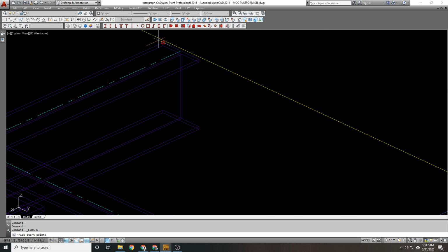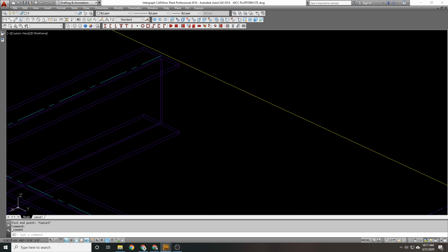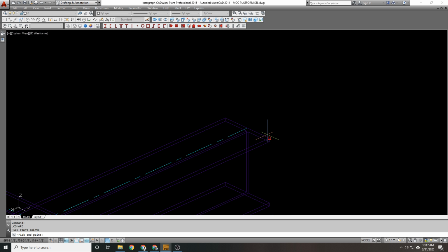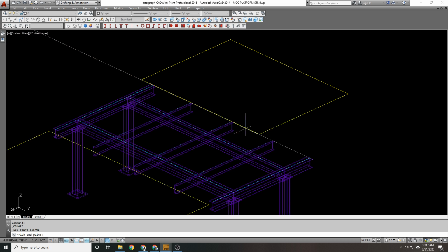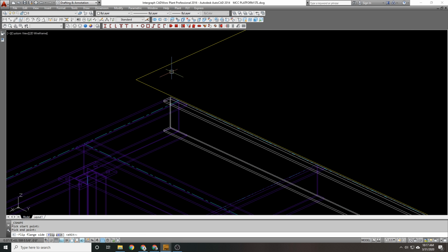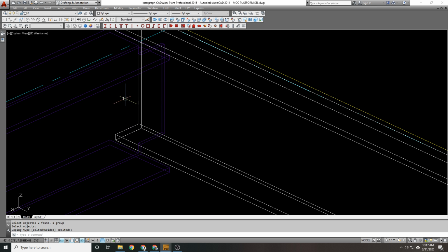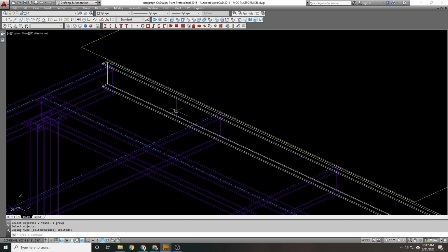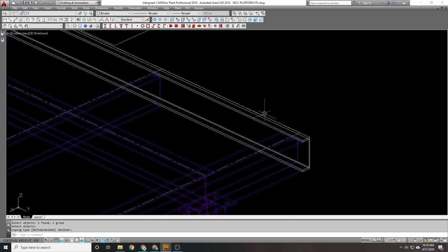So I'm going to pick a point from, again, the channel has to attach, let's see, not here, but this way. The channel has to be, oops, I forgot my rotation was still on. Here to here. And we're correct. This has to be coped into here so that we can put a shear tab here and they can access the bolts on the sides. So again, I'm going to cope here, here, here, and do it bolted. Okay?